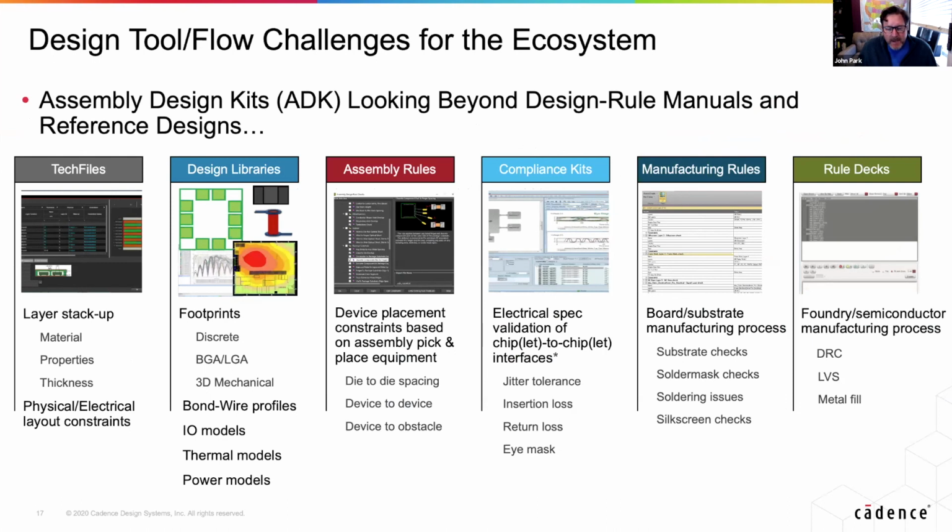Another kind of gap in the flows as we look at them today is this term ADK, or assembly design kit. So this applies more to the ecosystem. The chip designers on the call know what a PDK is. Most chip designers wouldn't even start a design without a PDK. It gives you the libraries.